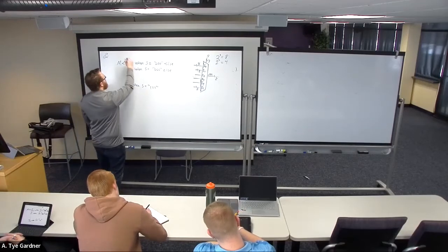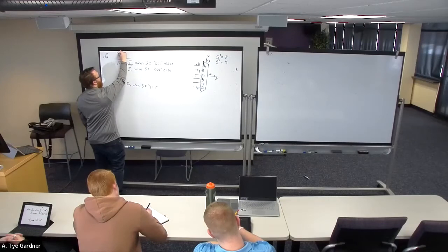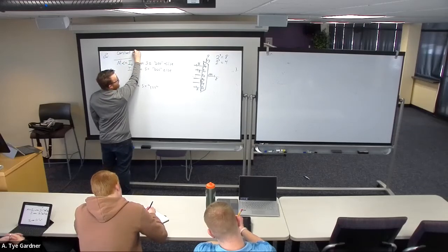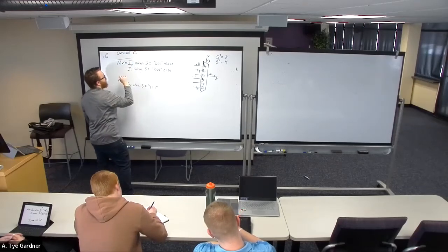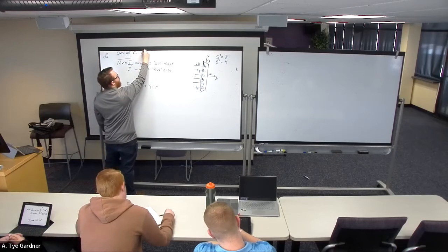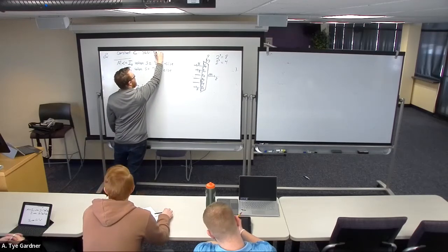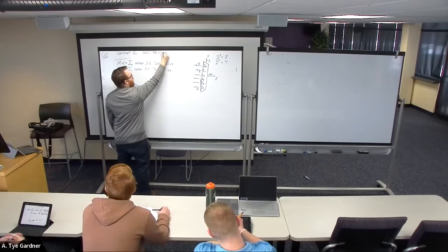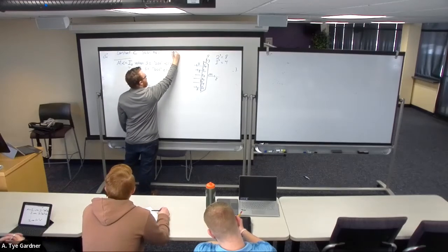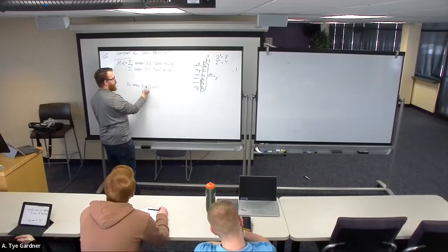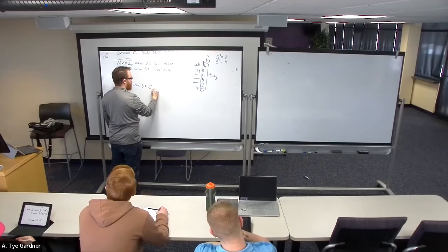So if I was up here, I had declared a constant C, I think C is a good letter in this case, constant C of standard logic vector size 3 or 2 down to 0, and its value is 111. Then instead of saying S equals 111, I just say when S equals C.